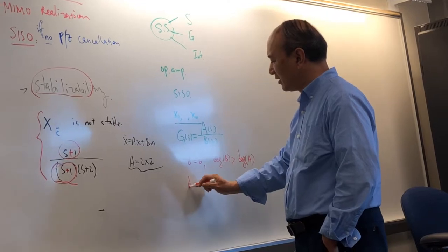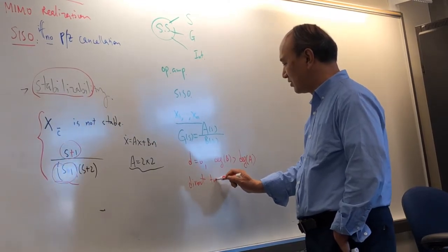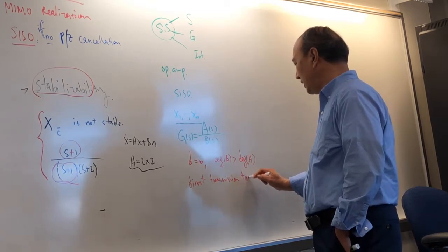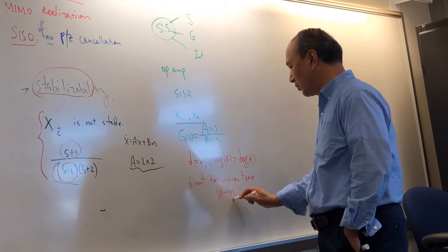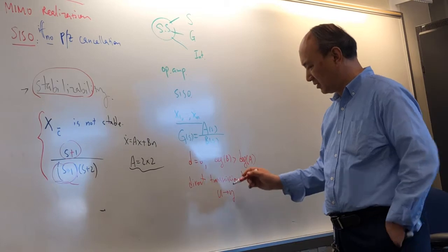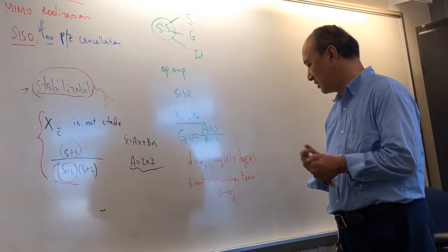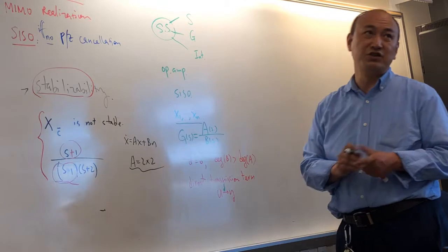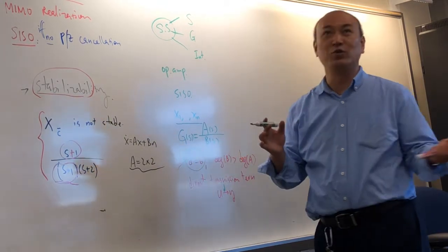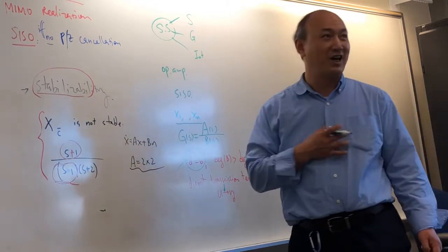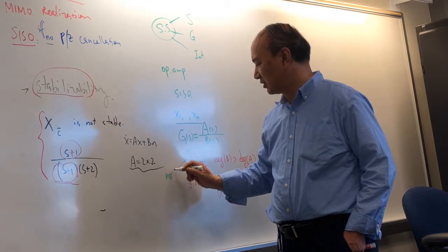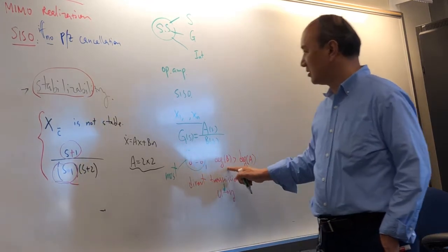And this is called the direct transmission term. This one goes directly from U to Y without going through an intermediate step. So this goes to this D. Okay, this D. And in most engineering systems, we don't have this D. D is 0 in like 99.99% of cases, as I have seen so far. Okay, so majority, most systems are strictly proper.